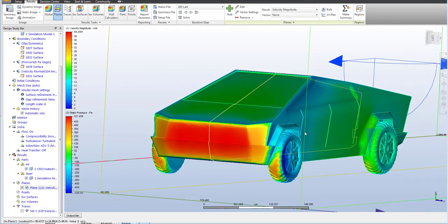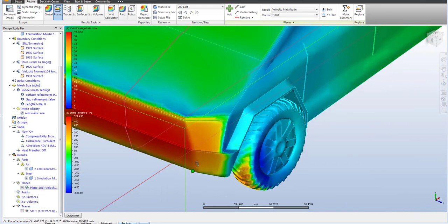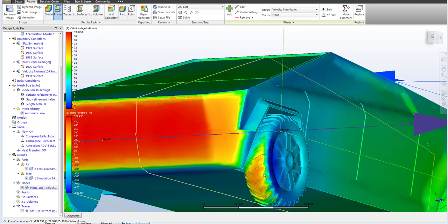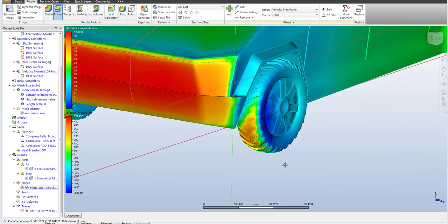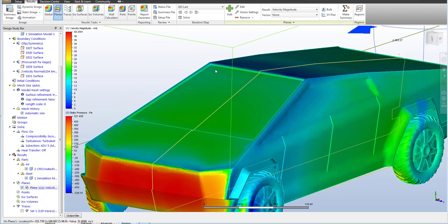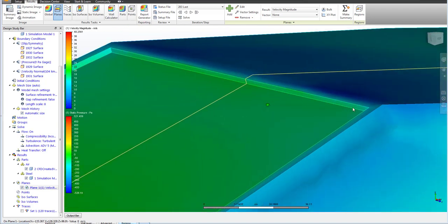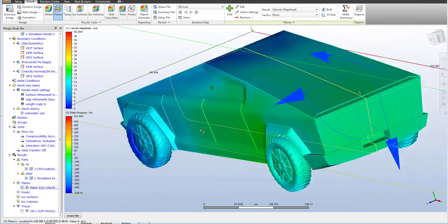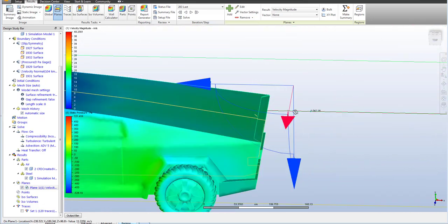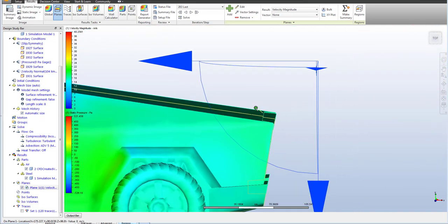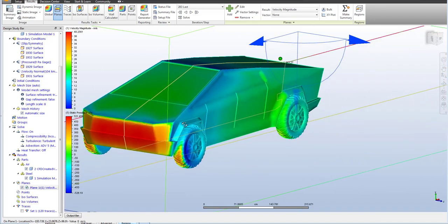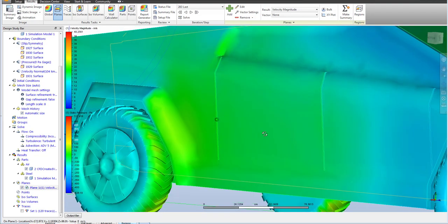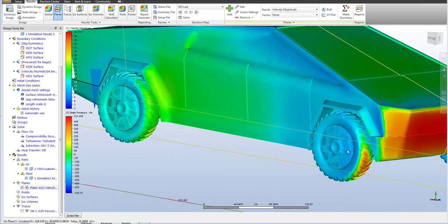as you can see, there is a lot of detail that I did not simplify, like the bumper, the fender, and the shape of the rotating wheel. They also influence the drag force, and also the front shape here, with many sharp edges. I think because of that, the detail of the shape of this car makes the drag coefficient a bit higher than predicted.